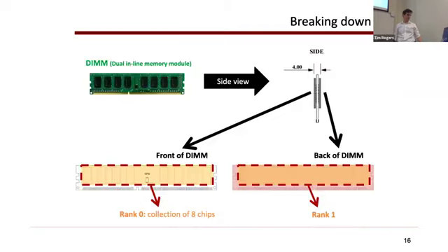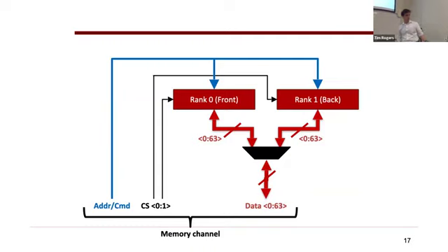We went through the fact that, so here's your DIMM, right? And the DIMM in this example has 2 ranks. And a rank is sort of like a big logical chip. It's like if you bolted all the chips together and you got one giant chip, they all operate together, because we can't actually build a chip that's big enough to service, for example, an entire cache line, right? We can't feed out 64 bytes from this thing for even a CPU cache line. So we feed out 8 bytes per chip among 8 chips, and then you get 64 bytes, okay? And we'll see how that works in a second.